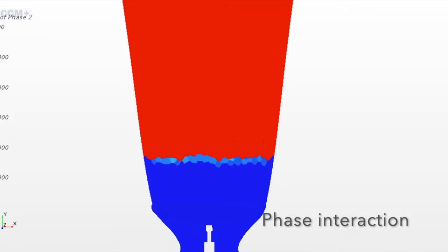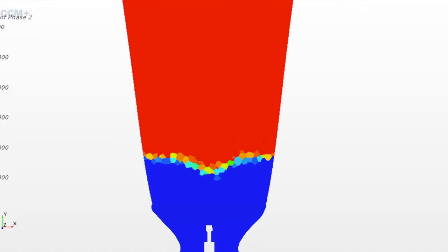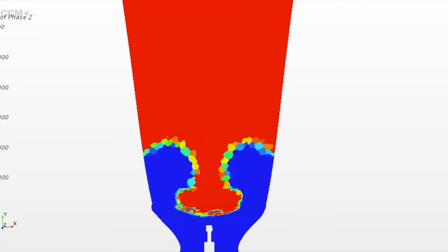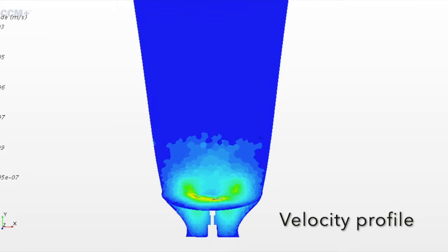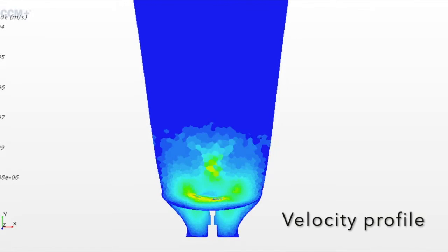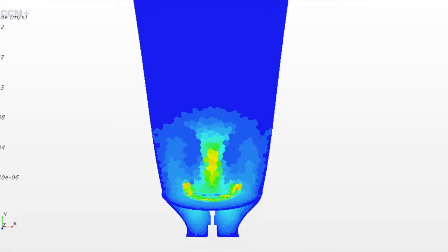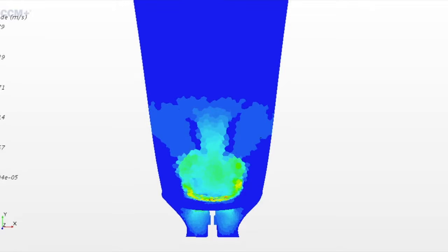As for the honey, the interface behaviors are similar to water, in which a vortex is formed. They show that although honey presents a higher viscosity, the ascent of bubbles inevitably results in an organized flow pattern and, as a consequence, in a vortex. As the velocity profile shows, a maximum speed is obtained in the innermost part of the tank. As displayed in water, this zone presents the highest velocity of all, due to the no-slip conditions assigned to the first liquid layer adjacent to the wall.